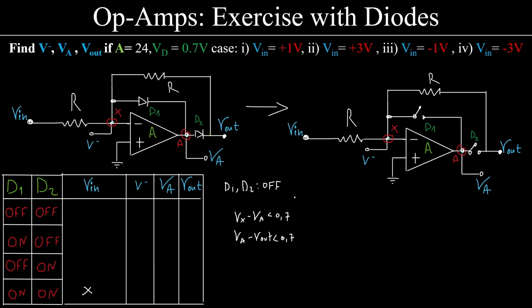Now, there is the second golden rule of the op-amps, which is this condition for the outputs, and we are going to go ahead and replace V plus with 0, V minus with Vx, and we are going to have that Vx is equal to minus Vout over A. Now, we have three different equations. Also, before I do anything, I notice something here.